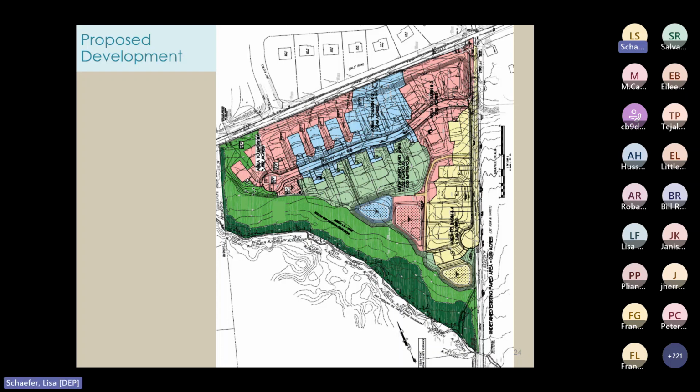However, the placement of the basins is too far from the source of the runoff. Plus, the GI BMPs should be distributed throughout the site and not grouped so close together as they are here. Why? Well, the motor vehicle surfaces are what are generating runoff with TSS that requires treatment, and the GI BMPs need to be near them. Now, if rooftop runoff, let's say, or other impervious cover that's not motor vehicle surface is commingled with the runoff from the roadways, then that commingled volume must be treated. But no information was provided regarding the roof drain off, so I'm a little concerned for this.